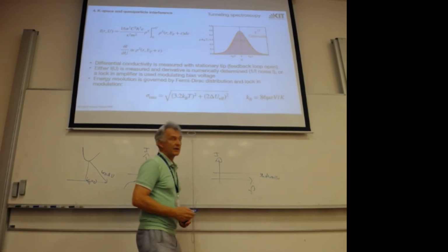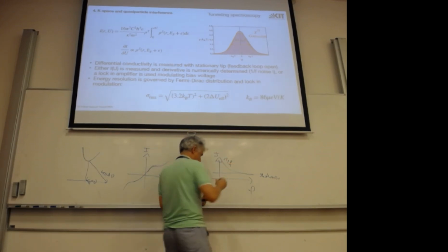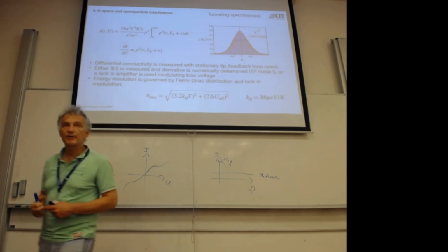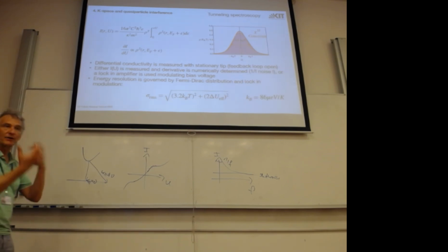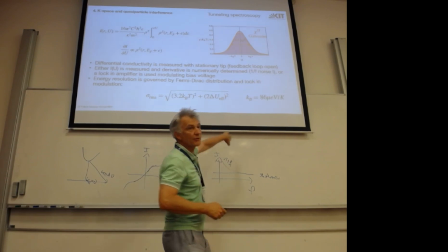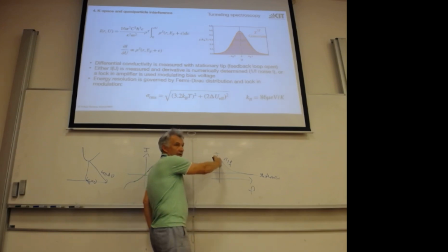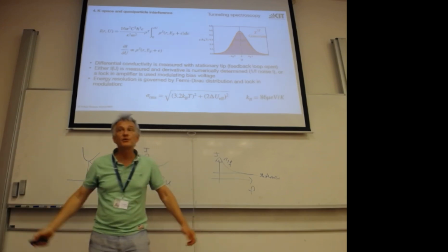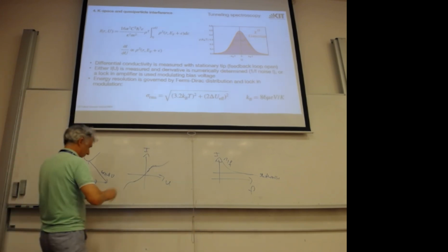But all of the technical instruments contain one over F noise. Yes, so you have variations in your amplifiers. Some atoms are rearranging in your transistor, and this actually explodes. So if you average very long, it means you pick this Fourier component here, and it's the most stupid thing you can do. So instead, what you do is